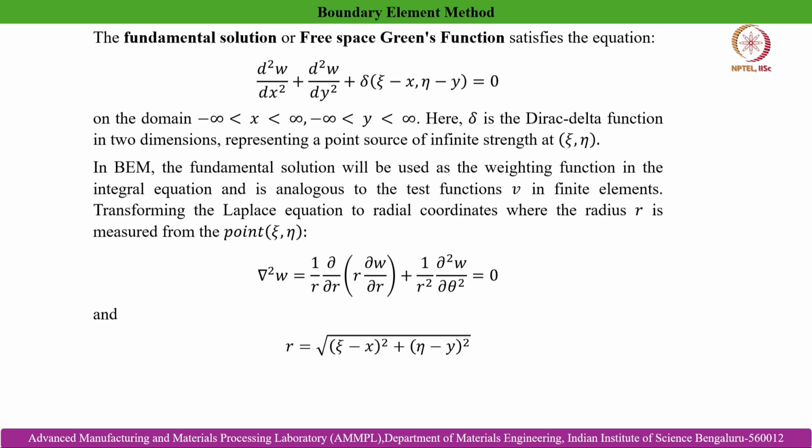Here delta is the Dirac delta function in 2 dimensions, representing a point source of infinite strength at (eta, zeta). In the boundary element method, the fundamental solution is used as the weighting function in the integral equation, as I told you earlier, and is analogous to the test functions v in finite elements.